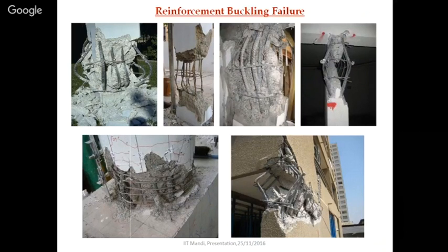These are buckling failures, rebar buckling failures, which occurred due to improper confinement. Now you can lift the building up to a certain limit, then you can curtail the bar, provide a new bar, or straighten the existing buckled bar. You can connect the broken bars, or connect the new bar with the old bar, you can use any technique.